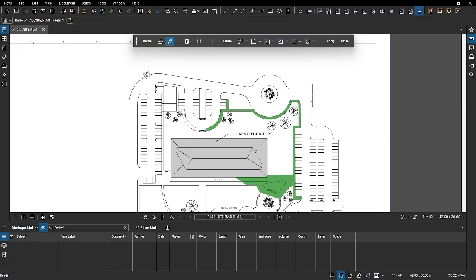The fill is then poured into an area until it hits the boundaries. As the fill extends in all directions, move the mouse around and note how the fill follows the direction of the mouse until it hits the lines in the content. You can paint over the lines and content to continue filling. Click and drag over the lines to finish up the fill for this area. Hit the Escape key to exit the Fill tool.